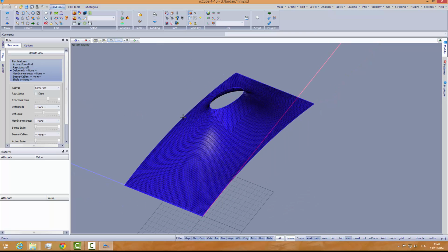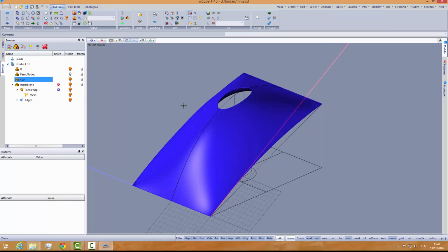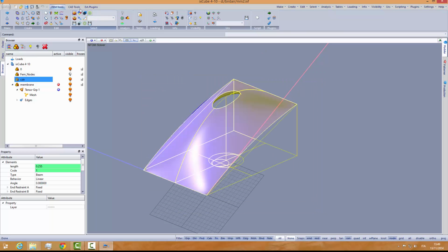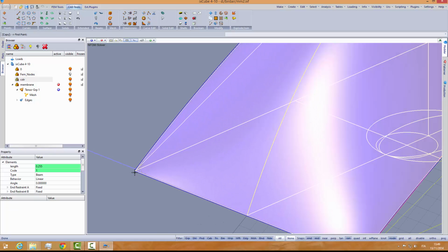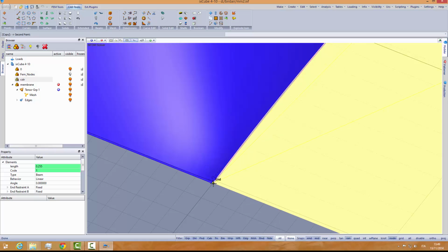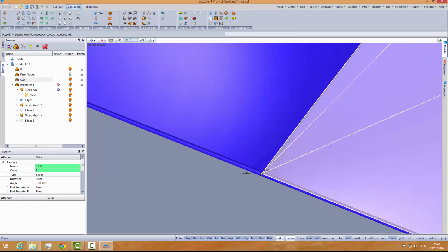Let's take off the stresses and hide the mesh. I will activate now snap to node, and if I unhide, I would like to select everything here. I go into the CAD tools, use the copy tool, and copy from here to here to here.